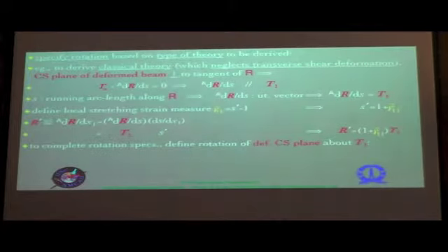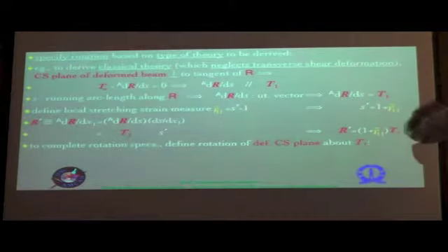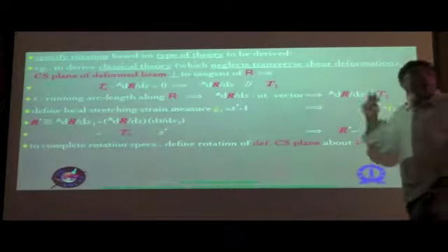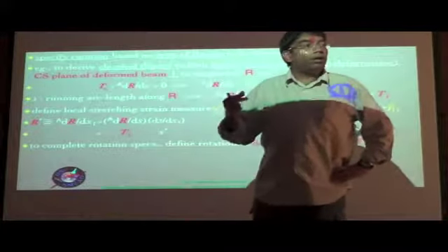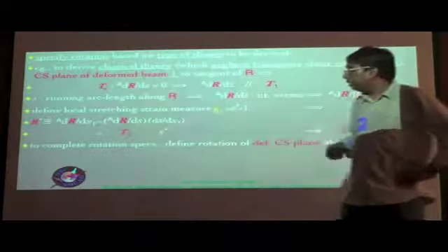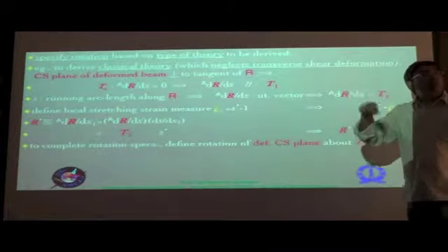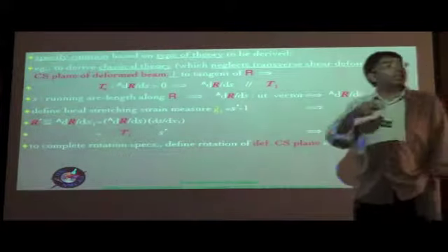To complete the rotation specifications, you need of course another rotation, which is to define the rotation which is taking place about T1. And that has to be accounted for by the fourth constraint. So remember, we already invoked the three constraints, that is Wi average equal to 0 when we defined, let's say, u for example. But we have not yet talked about the rotation constraint, which is x2w3 minus x3w2 integrated over the cross section equal to 0.